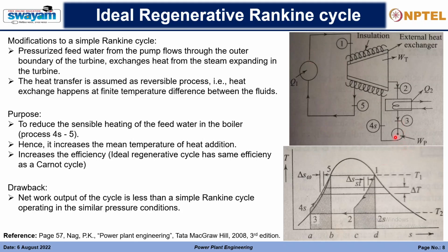So we are not increasing the pressure. Sensible heating is increasing the heat of the water at constant pressure, right? That is why you use the specific heat capacity, Cp, which is used only in a constant pressure application. So this part is a constant pressure application; we are not increasing the pressure here.